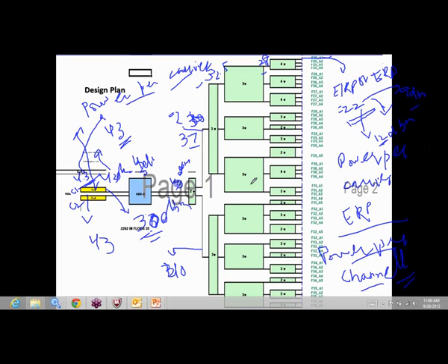So this is basically a schematic. We can do the calculation on the basis of total carrier power, which is called composite power. Okay, we can do it. So all this calculation was done on the basis of power per carrier, so power per channel. Okay. And we understand what is power per channel, and we understand what is CPICH power. What is EIRP? So we understand now how to calculate ERP or EIRP, which is called power per channel, and which is also CPICH power, and how to calculate ERP for CPICH power. So we understand those things. The only thing remaining is the concept of composite power.